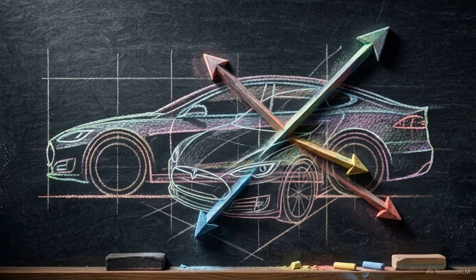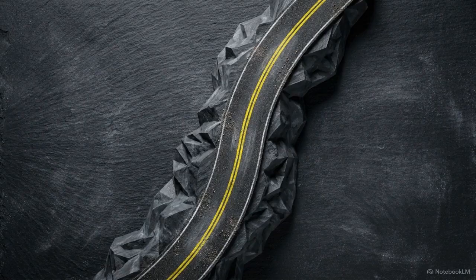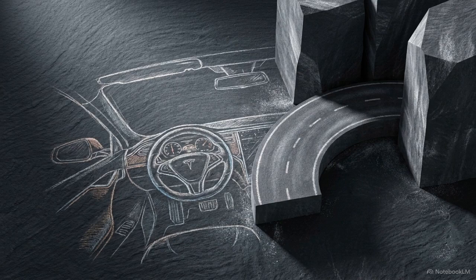Because engineers must calculate the high-speed kinematics of 3 separate vehicles interacting at once, the total required overtaking sight distance is drastically longer than stopping sight distance. In mountainous or highly developed areas, providing full overtaking sight distance is often impossible. In these restricted zones, engineers rely on a fallback standard, intermediate sight distance, or ISD.